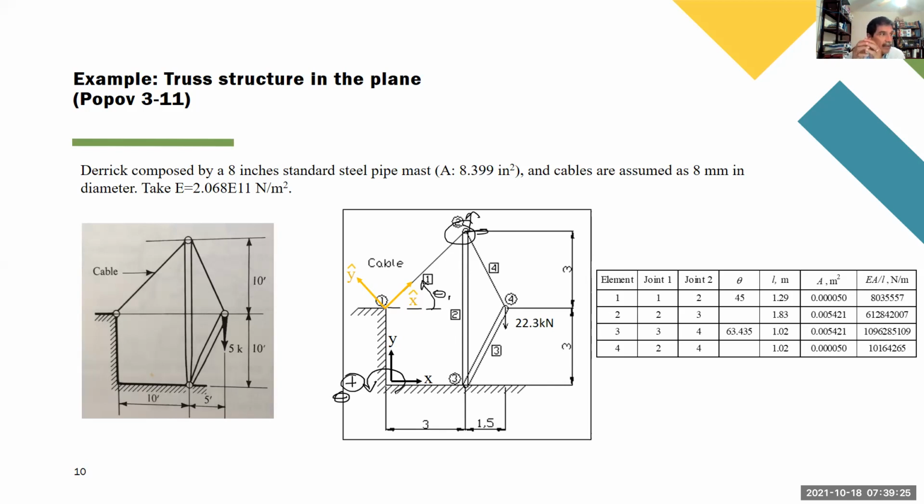And in that case, what you can do is try a value, calculate, and then check if the stresses and the displacements are good enough. If the stresses are very high, you have to increase the size of the element, the area, and that will probably reduce the stresses. So that depends. But in general, that's a geometric characteristic that depends on the depth of the problem.